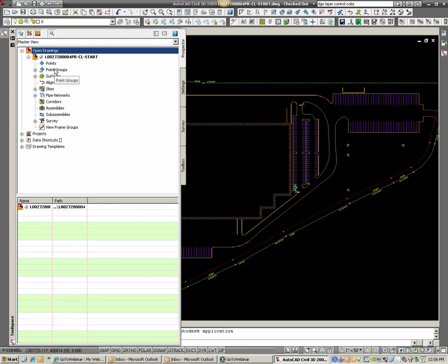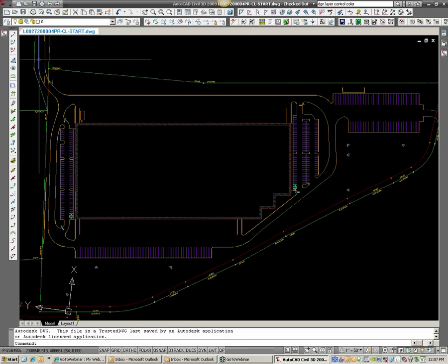And what I'm finding is that since you have a corridor model in your centerline drawing, your profile centerline drawing, it's the easiest thing, wherever you have that corridor model is really where you want to have the rest of your feature lines for grading. So if you don't have that situation, you want to put your grading in your GRD file, but don't feel it's too restrictive to get it to where it feels more appropriate. Wherever you have your corridor model, that's where you're really going to have the rest of your site grading because they sort of mesh together. So let that be as may. If you do have questions about that, don't hesitate to give me a call.